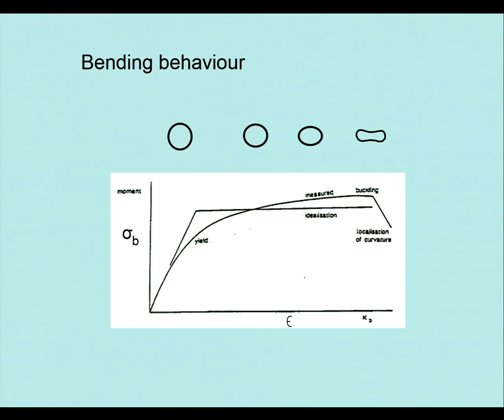How do we get bending? Well, we get bending when we're laying, which we'll see in a little while, and that's the time when we've got to be careful. On steel risers, catenary risers, we've got depth pressure and we've got bending combined, so that's a live load. Normally when we're laying, you design your installation technique to make sure the bend stress, or maximum stress during laying, is no more than 80% of the yield. That's a normal, typical construction stress.